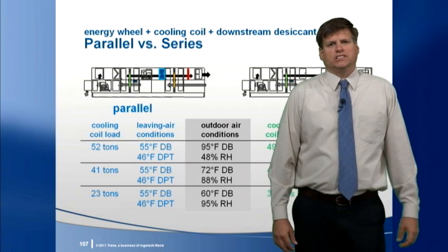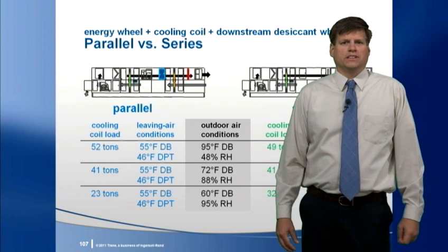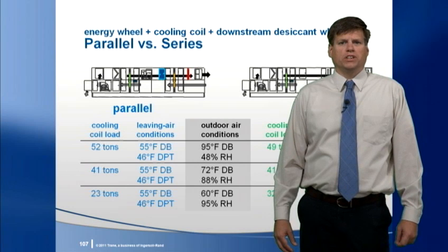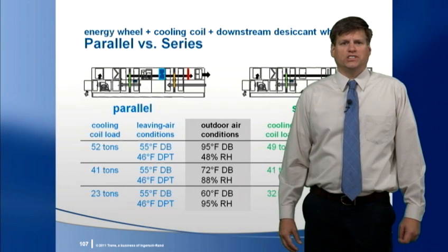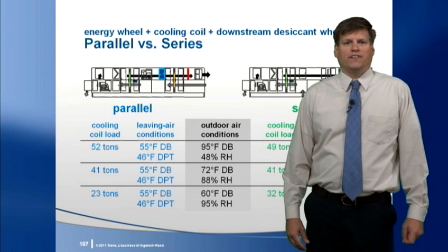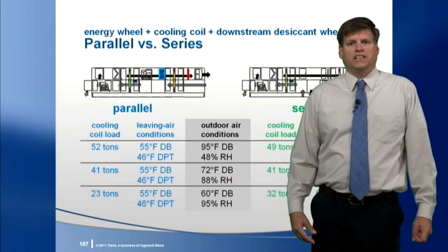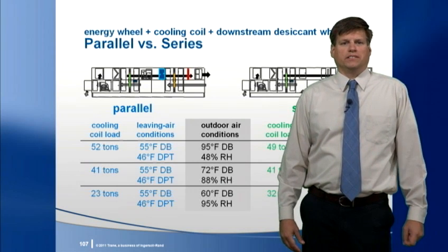However, in most applications, performance on design day and during hot weather is most important, since this is when the load on the cooling equipment is the highest and when efficiencies are lowest. Saving 3 more tons on a day when it's 95 degrees outside may be more beneficial from an energy perspective than saving 9 more tons on a 60-degree day.